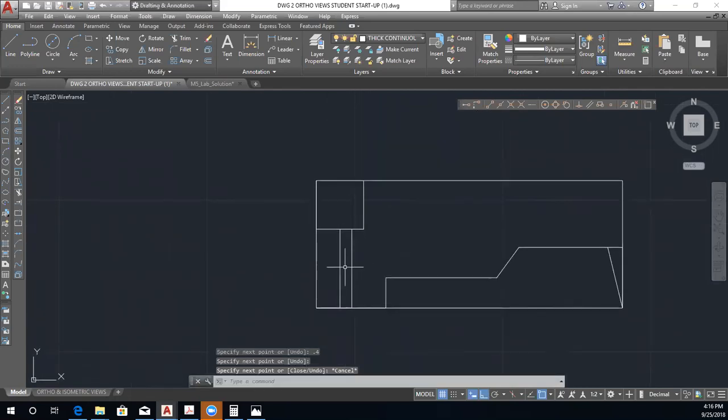And then we can actually offset the two lines. So we will do an offset, select objects, we want to offset this. Oh, actually escape, okay, offset again. And then first it says specify distance. The diameter is 0.4, so the radius will be 0.2.